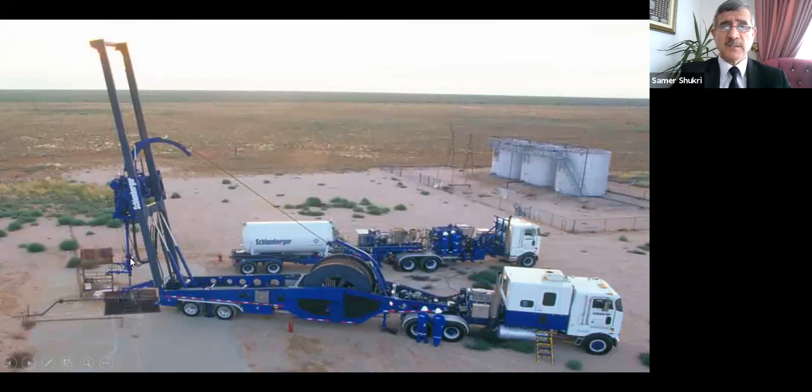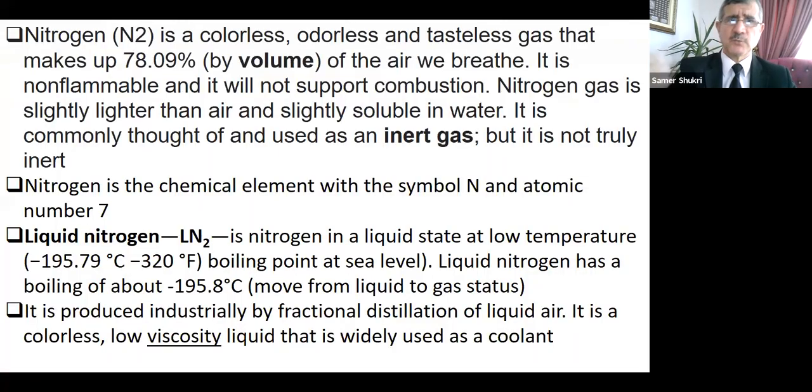So even if we want to keep the coiled tubing inside the well, we have to keep the pressure inside it higher than or equal to the pressure in the annulus between coiled tubing and tubing. In this case, we protect the coiled tubing from damage, and we can resume the operation after they fix the problem in the station. This is one case that happened with me. I transfer it to you, and I can talk more about it.